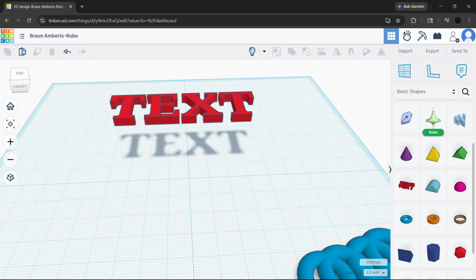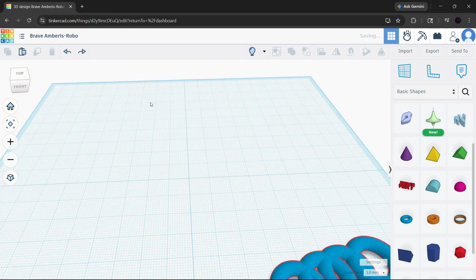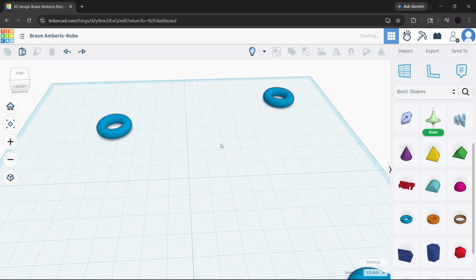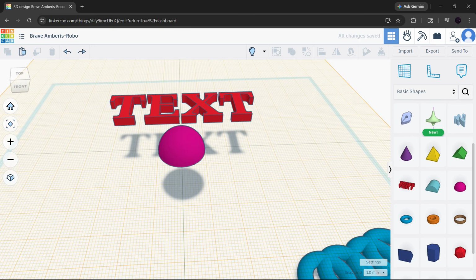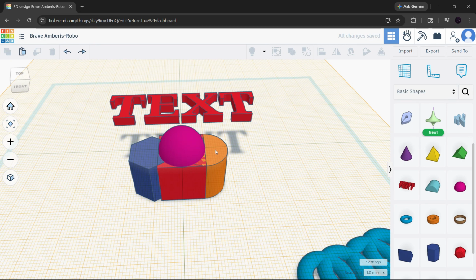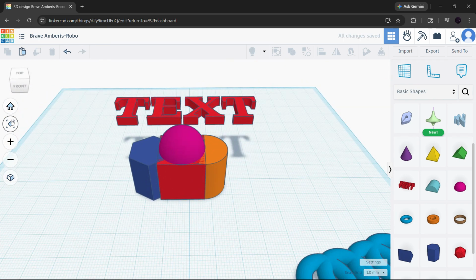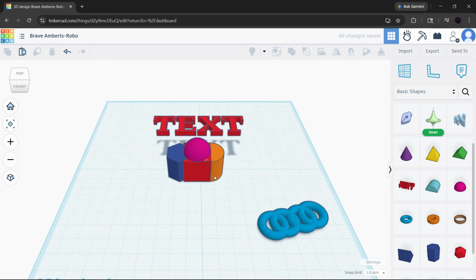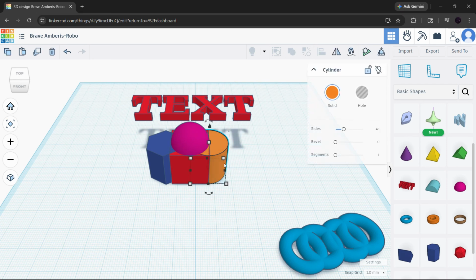fast. You can also use Multicolor to make your design look like it has separate layers, while still keeping everything grouped together. To do this, select your grouped object and look at the solid color option in the inspector window. When you enable Multicolor, Tinkercad keeps the object grouped, but each part can still show a different color. That makes it easier to visually separate the layers in your design without having to ungroup everything. This is perfect for presentations, prototypes, or any project where you want the design to stand out clearly. You get the organization of grouping and the visual clarity of different colors at the same time.